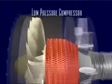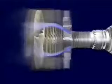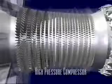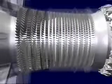Meanwhile, the other 15% of the air has entered the first component in the engine's core, the low-pressure compressor. Here, the air passes through several smaller stages, each consisting of a set of rotating blades in between a set of stationary blades. Each stage compresses the air, forcing its temperature and pressure to rise. After passing through the low-pressure compressor, the air enters the high-pressure compressor, which rotates faster and is responsible for 70% of the total pressure rise.